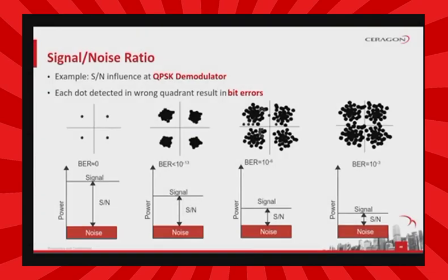The signal-to-noise ratio measures the difference between the useful signal level and the level of noise caught by the receiver on the transmission channel. In our presented example, we take the case of one modulation, QPSK, to show you how the SNR level variation influences the bit error rate observed, which actually defines the quality of the transmission. Bit error ratio measures the ratio between the erroneous received bits and the total transmitted bits within that communication.